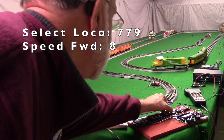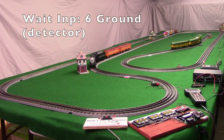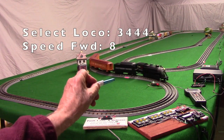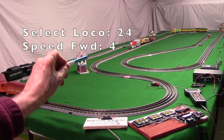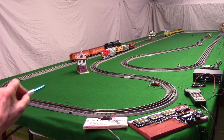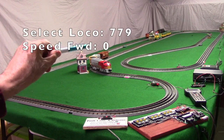I'm going to open the repeat switch. Now that loco's already selected, so when that crosses the detector, the controller will send a speed forward 3 command to slow that down. Select 3444, the steam loco, speed forward 8, select loco 24, the F3, speed forward 4. Now we're running a 14-second time delay, and when that ends, we'll send speed forward 0 commands to both of those locos.